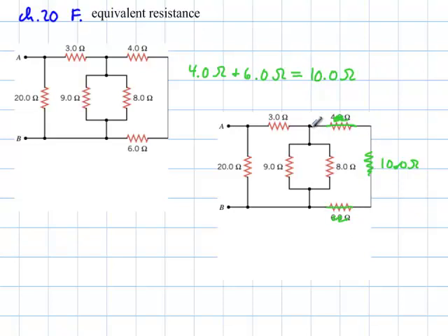because now I realize that because of this junction here, which is virtually the same as this junction here now, or actually is, the current splits up into three parts. The current that comes in here goes through this one, this one, and this one, and those three parts come back together here, and here, and here. So these three resistors are actually in parallel.